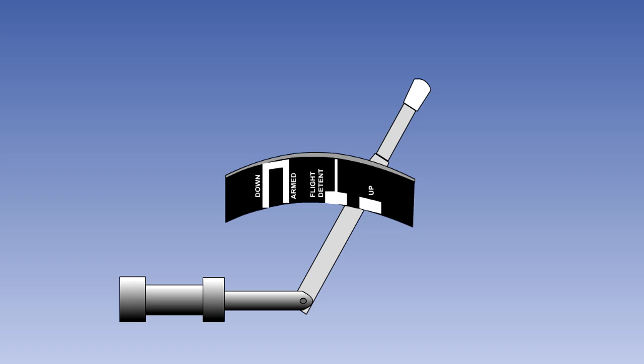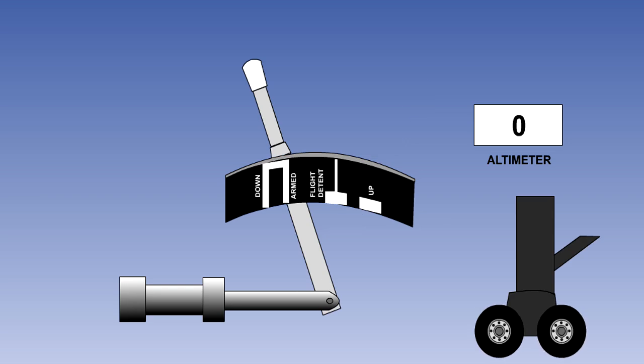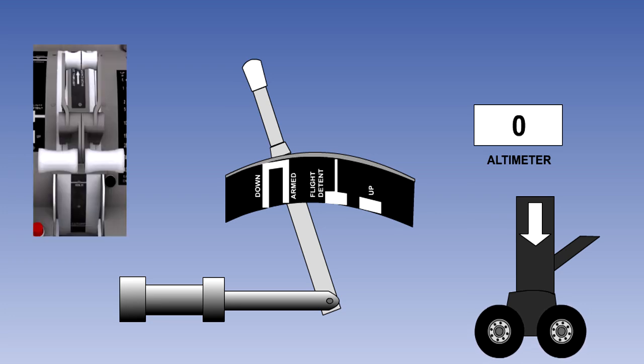Different aircraft types use various different parameters. They will usually include 2 or more of the following: the radio altimeter reading less than 10 feet, the wheel brake anti-skid system sensing wheel spin up, the air ground sensing system giving an on-ground signal, and the thrust levers being fully closed.